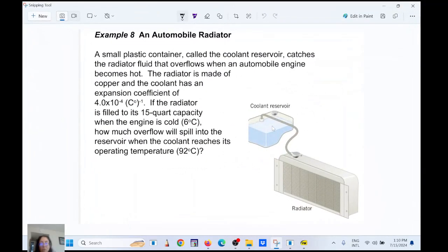So for the coolant, let's do the coolant expansion. The coolant is here, and it will overflow because liquids expand by a lot. You see, 10 to the negative 4 is a lot. So you have delta V equals initial volume times beta, that coefficient here, times the change in temperature. So delta V equals the initial volume, which is 15 quart capacity. Quart is the volume. Beta is 4 times 10...